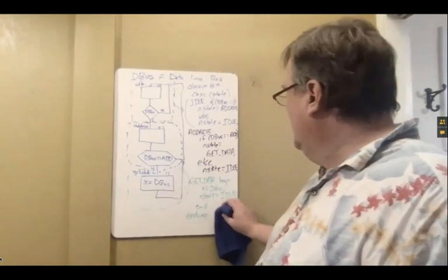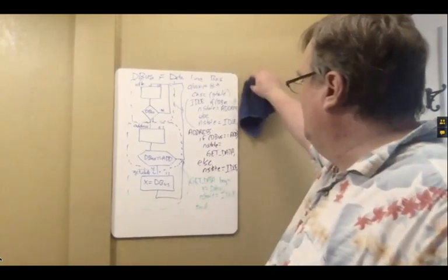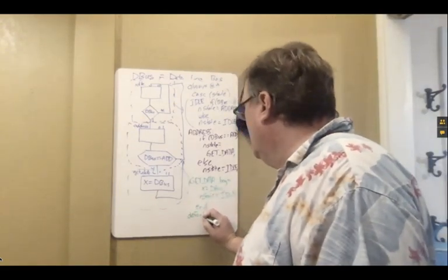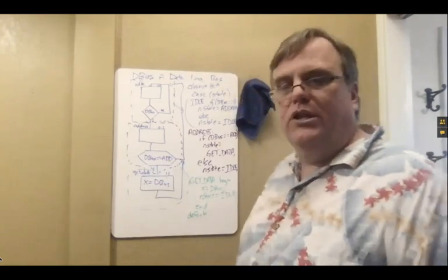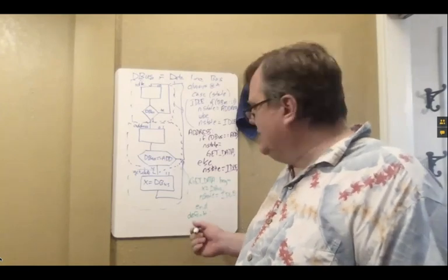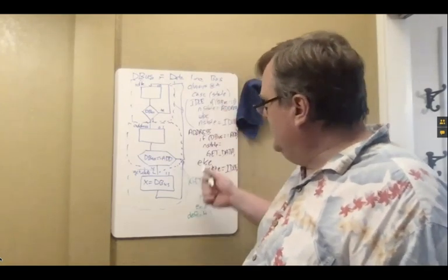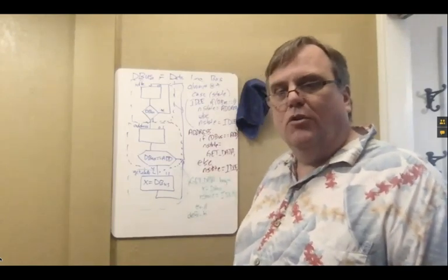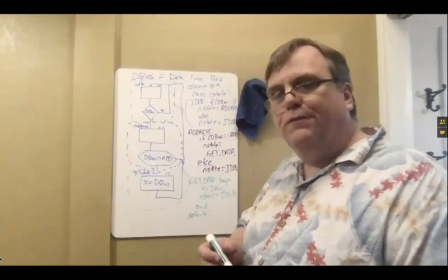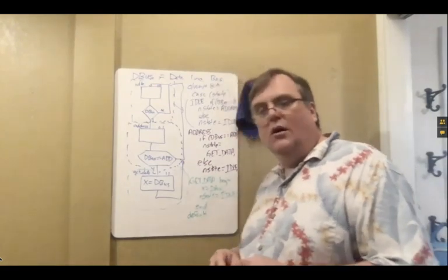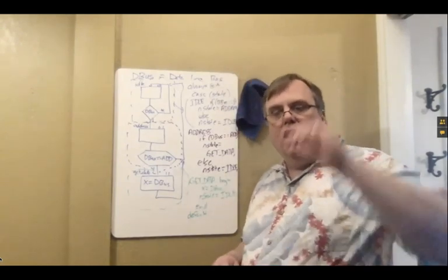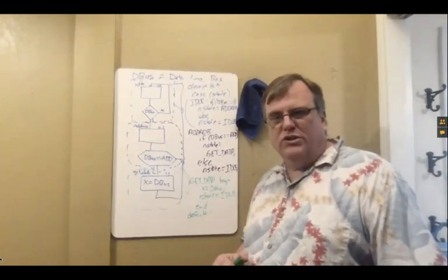So what I really should do to remove that possibility is to add a default. What should I put in the default? Remember, in this default case, I can only get there if I'm not in a legitimate state. So by definition, I'm in a bad place. There's a few reasonable things to do. One simple one, then some more complicated ones, but all of them justifiable. Anybody got an idea what they might want to do under this default case?